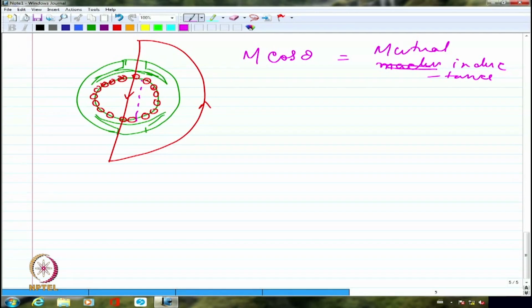So, what we do in a DC machine is to make them exactly at 90 degrees to each other. So, d LSR by d theta, which is M times sin theta, has theta always made 90 degrees by inserting the commutator. That's what we do in a DC machine.